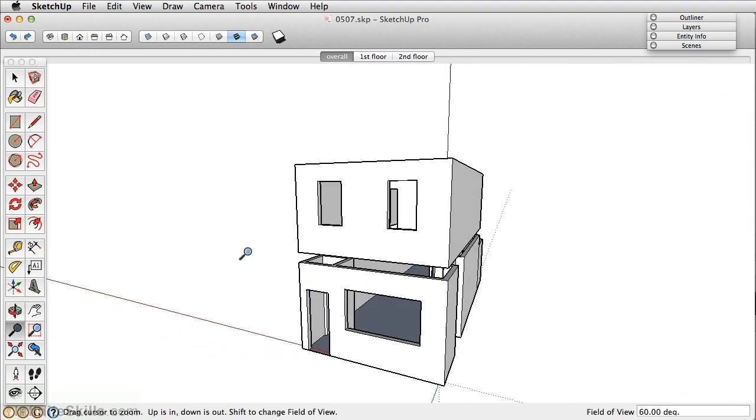So as I mentioned, you can view this in field of view, or you can look at it in focal length. I like photography, so I try to think in focal length. For this specific illustration, let's say we wanted a rendering of the exterior here, and we wanted it at 35 millimeters. To change it, let's type in 35 mm and press enter.